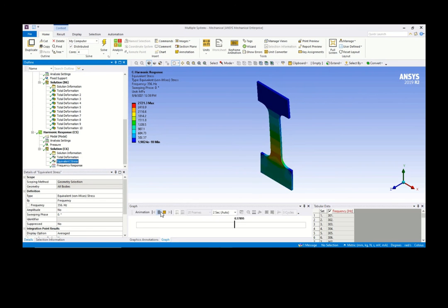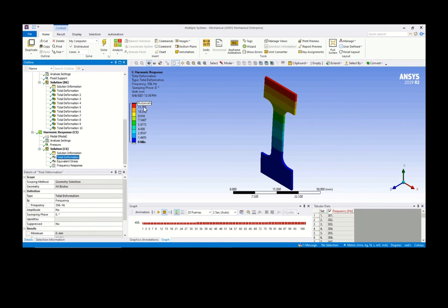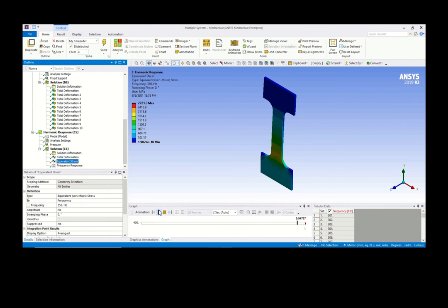Okay, megapascal. Can you see that? So the effect of frequency is that. Unfortunately, if you excite the specimen itself under a harmonic excitation at the frequency of 356 hertz, it is very close to, or coincides with, its first natural frequency at 356.31 hertz. Then it will generate very high vibrations, maximum at 13 mm, and very high dynamic stress at around 2,700. Right, so that is what it means.